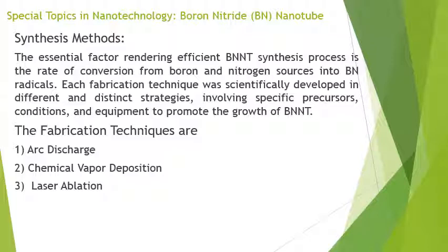So it is not surprising that the chemical vapor deposition process for boron nitride nanotube growth is relatively similar and reminiscent of carbon nanotube synthesis. The difference lies primarily in the types of starting materials, growth conditions, and liquid and solid boron and boron nitride sources.